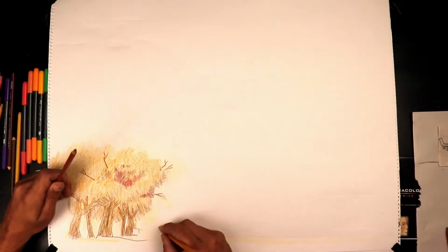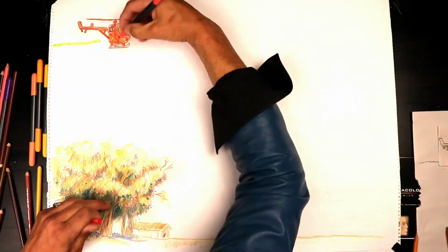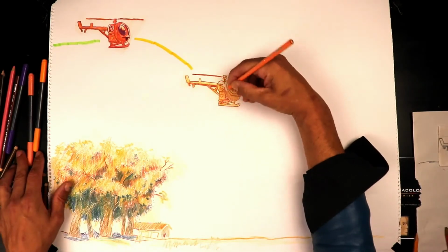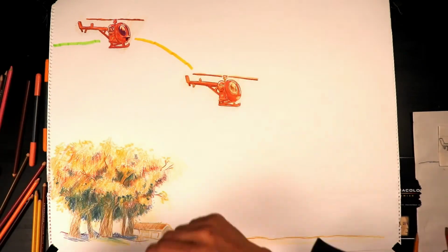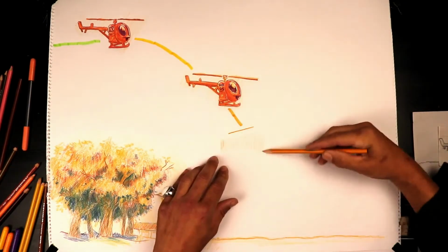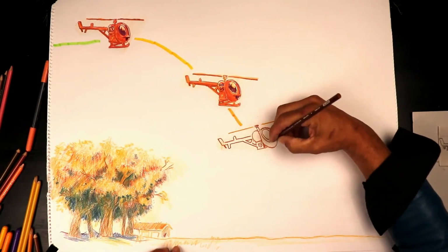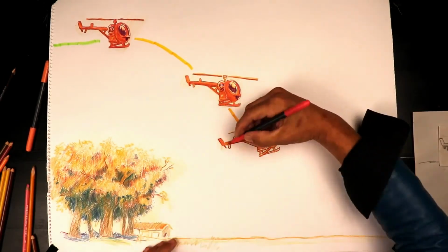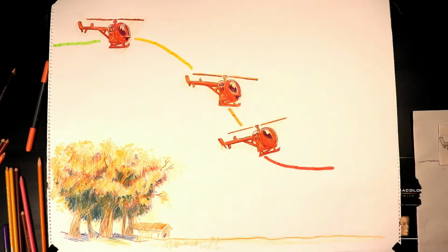You'll enter the auto, and we'll take the camera down to the RPM and show you how that will usually build just a little bit during the glide in a straight-in auto. In a 180 auto, during the turn, that RPM will always build, and we'll show you that too before we're done. So somewhere around treetop level, 40 feet, 50 feet, again, depending on what your aircraft manufacturer says, you're going to start a flare. And that flare is to slow the aircraft down to get ready to level it out and raise the collective, either to go to a full touchdown landing or to a hover.